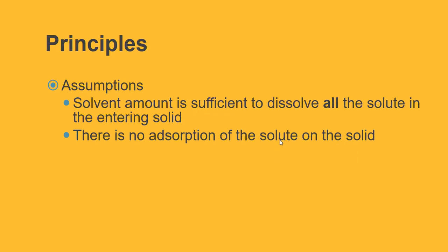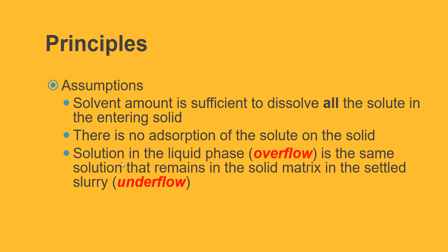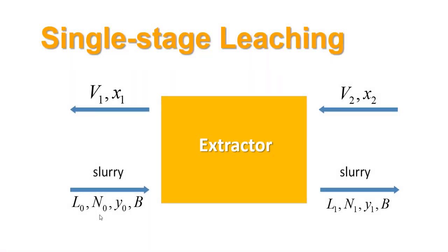The solute remains only dissolved by the solvent, and as such it will never remain adsorbed on the inert insoluble solid. Now, the solution in the liquid phase, the overflow, is the same solution that remains in the solid matrix in the settled slurry, which is the underflow, also mentioned already in the previous slide.